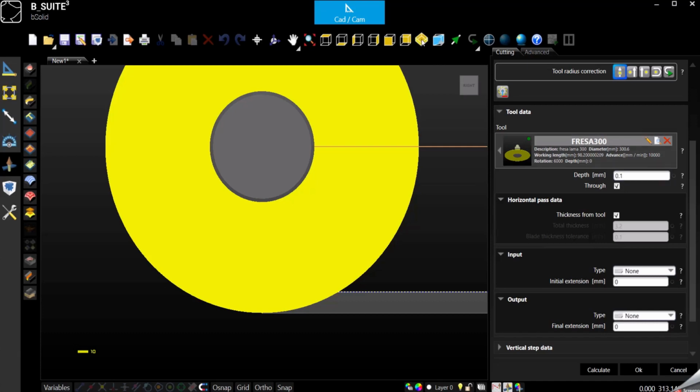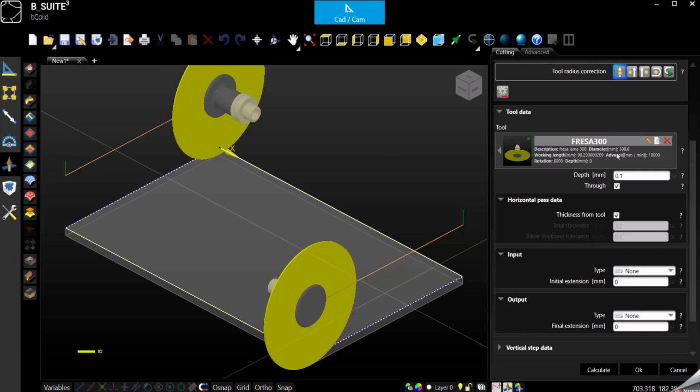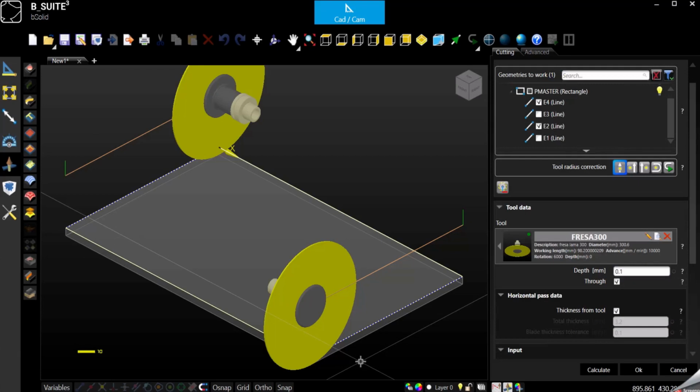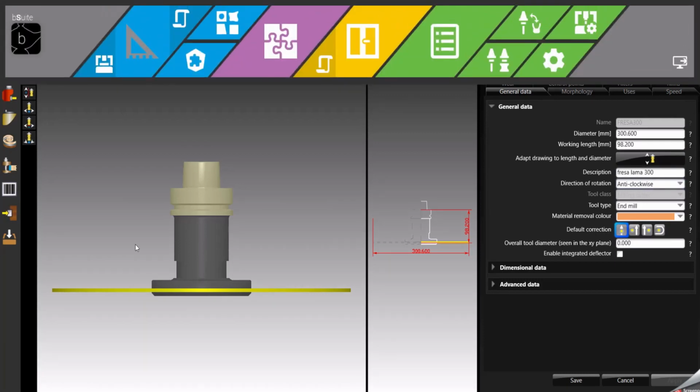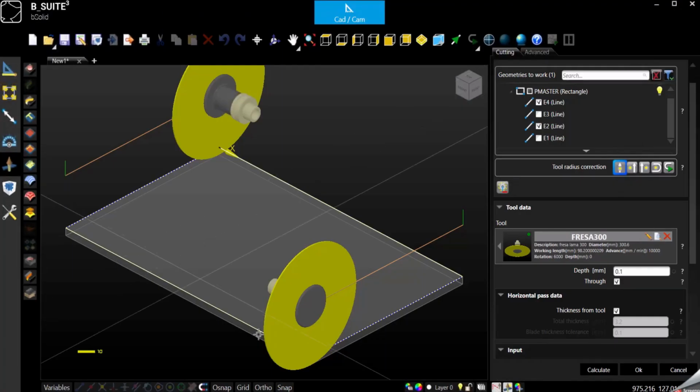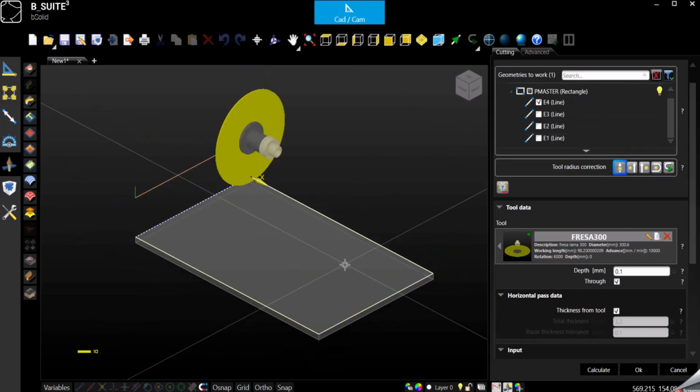Another important thing to talk about is the cutting direction. So as you can see, I didn't specify anything, and based on the rotating direction of my blade, which in my case is counterclockwise, but eventually we can go double check. So edit, blade, you see counterclockwise. So let's disable one. All right, so we can understand better.